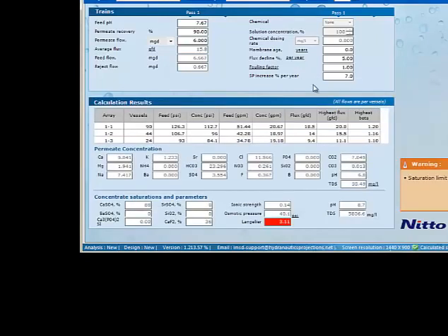And so we have some data now that's here, and so we've got the arrays, the vessels, the feed PSIs. You'll notice it goes high pressure down to lower pressure, concentration, feed in gallons per minute that's coming into the plant, the flux, so gallons per foot squared per day, highest flux and the highest beta values that are there. And here's the permeate concentrations. This is what we want. This is the concentrations of our anions, cations that are leaving the water filtration system. And we can also look at these other parameters.